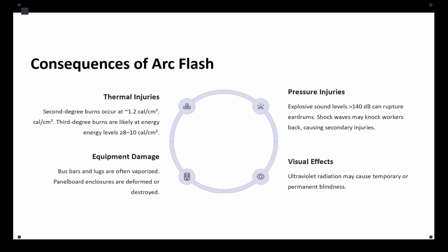A moderate arc flash can release around 20 calories per square centimeter in a fraction of a second. Actually, it would happen in 0.1 seconds. That's thousands of times more intense than standing next to a red hot burner. This is why incident energy calculation and the PPE rating actually matter. Human skin can only absorb so much energy before irreversible damage begins.